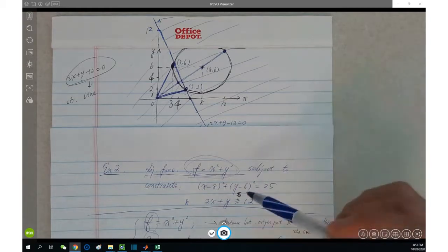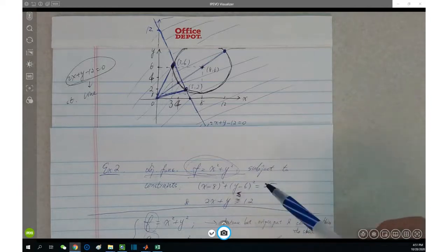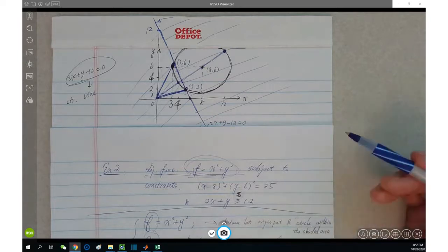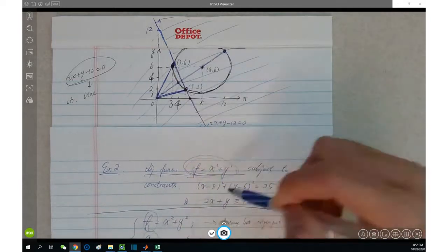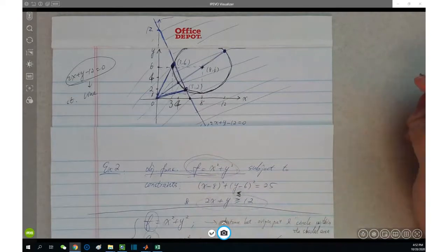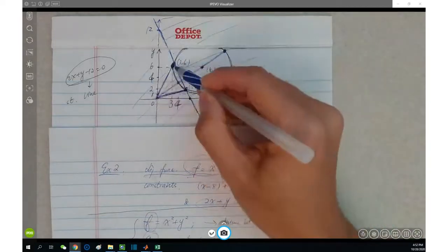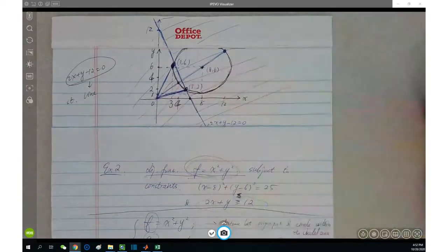In other words, if the problem gives you that like this, you're going to do the same. However, this is a tricky question. Why is it tricky? By observing here, you can tell you have this G here or not, there's no difference. Does it make sense? This G is shaded this way, and then you're shading here, and the minimum value is determined by the circle itself. It has nothing to do with this line. That's why the minimum distance now becomes 5.